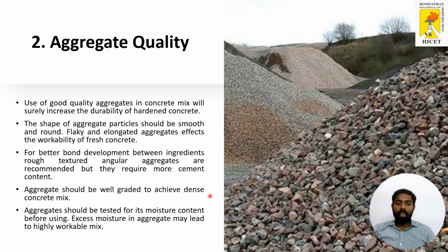And the aggregate should be well graded to achieve a dense concrete mix, and the aggregate should be tested for its moisture content before using, and excess moisture in aggregate may lead to a highly workable mix.